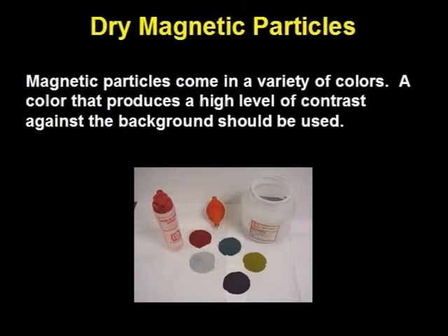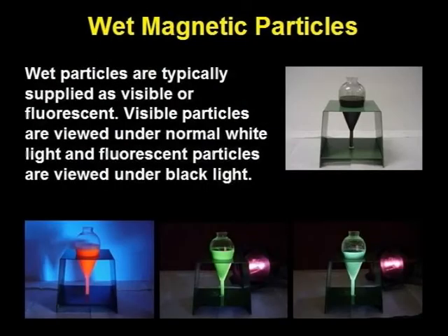The dry particles are dyed a variety of colors. The color is chosen to produce the greatest contrast against the background. Wet particles may be either visible under white light or fluorescent under ultraviolet or black light. The liquid holds the particles in suspension. The particles are not in solution. Left alone, the particles would settle out due to the force of gravity. Thus, the suspension is kept agitated.